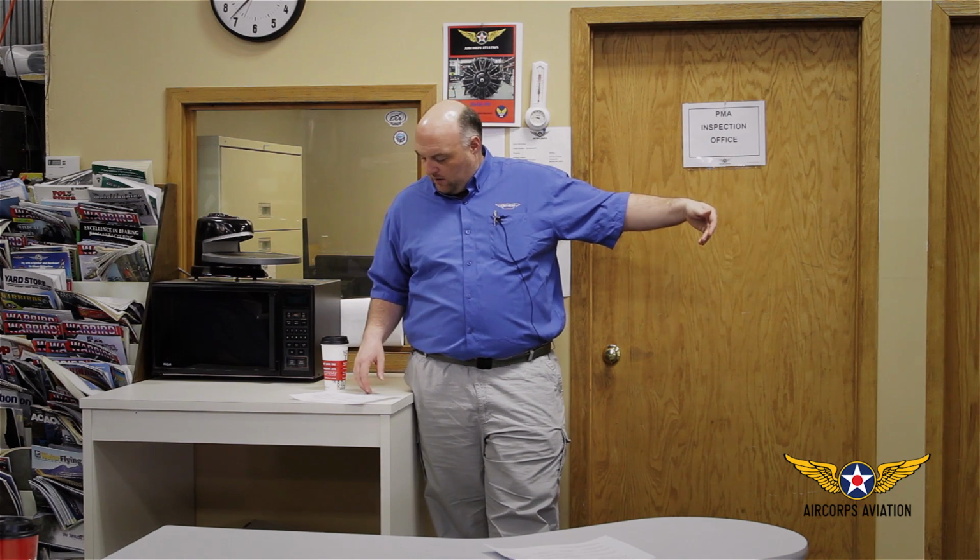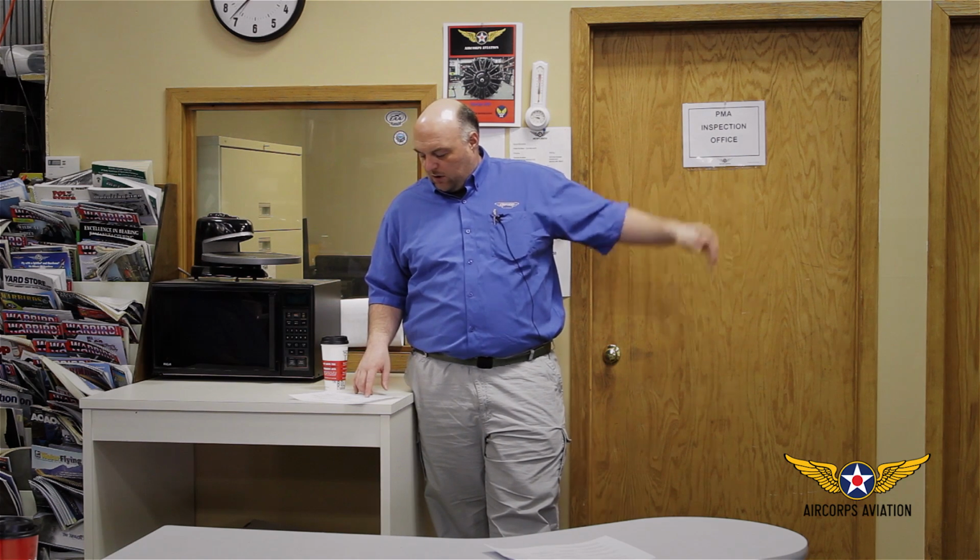Is the fit, form, and function the same? Does it still meet the airworthiness requirements for the original approval or not? And you get into the MRB process. And what you want to do most often, of course, is a -12 tag, which is a good part tag. That's an accepted part tag. Once that tag goes on there, it says FAA PMA, and that's now an approved part.